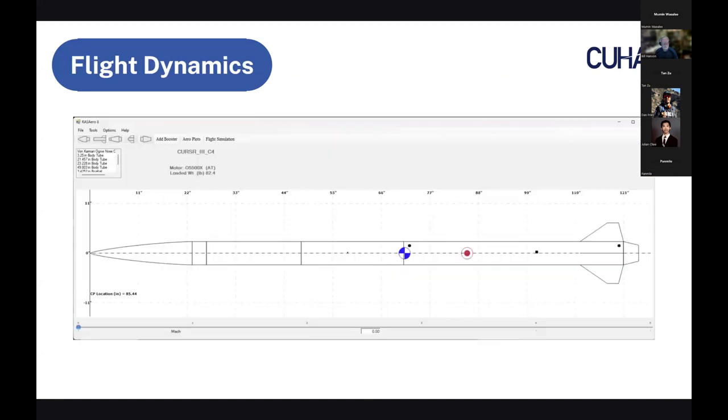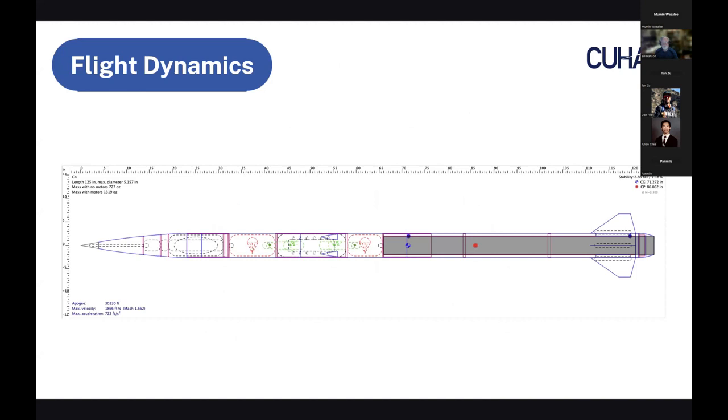What are they being fastened to? Is it just on the skin, I mean the carbon fiber part, or are you mounting them into some of your retainers or any aluminum? Are you threading the aluminum and attaching the rail buttons there? So we have a thread insert inside. We use the bar thread insert and mount it with the epoxy, so it will be secure like that. Okay, so in between that nut plate and the rail button, it's just the tube.